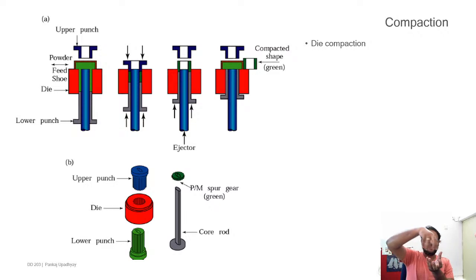The powder fills into the location where there is a gap, and the top and bottom dies push down, and the whole thing is compacted. At the microscopic level, these balls get crushed together, and they are held together by the binding agent that is put there, and by the frictional forces in the whole thing.